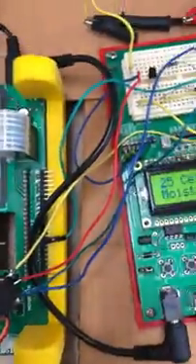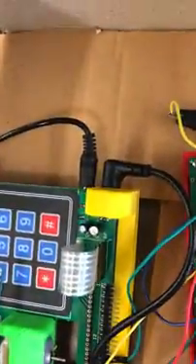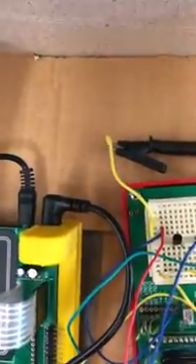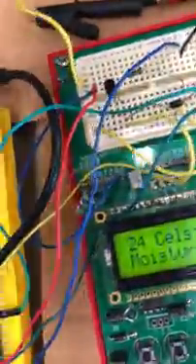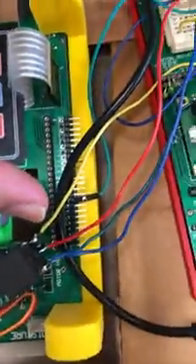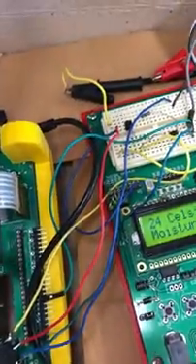And the third and last thing that I have used in this is the solenoid valve, which is further connected to the relay. If I talk about the first pin of the relay, which is the center one, the red one, it is connected to the ground, and the second pin, the green one of the relay, is connected to the 5 volt.